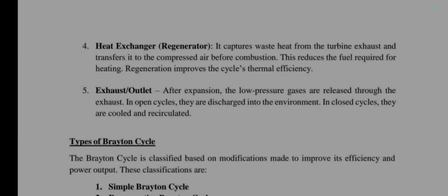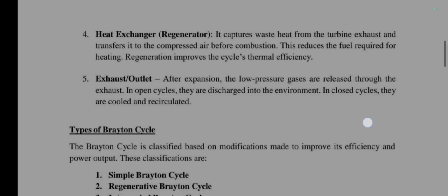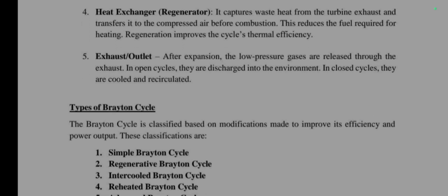Heat exchanger or regenerator. It captures waste heat from the turbine exhaust and transfers it to the compressed air before combustion. This reduces the fuel required for heating. Regeneration improves the cycle's thermal efficiency.